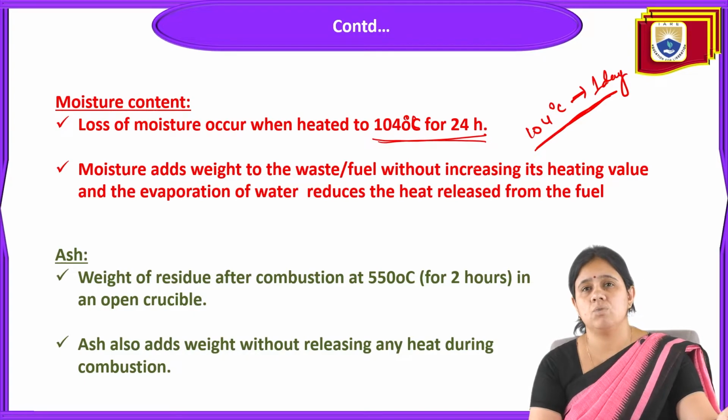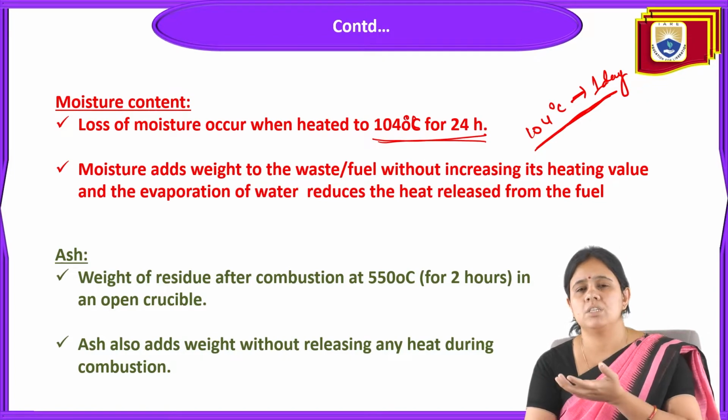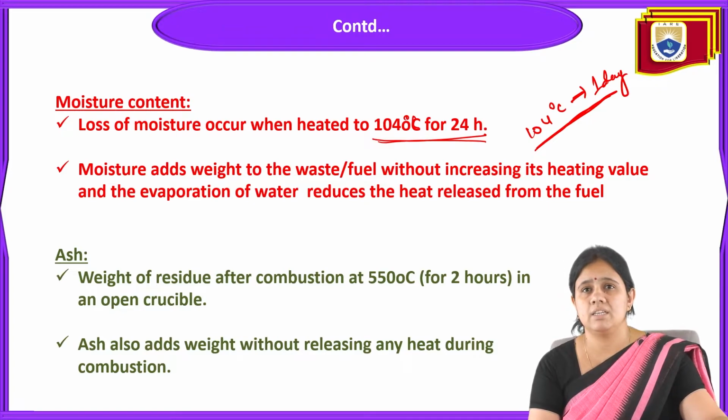And what is moisture doing? Moisture is adding weight and reducing the calorific value of the waste, and it is adding weight to the fuel without increasing its heating value. This means the heating value is not increasing, because the water content is already there, and the evaporation of water is going to reduce the heat release from the fuel. So this moisture will obstruct the heat, and the heating capacity will be reduced.